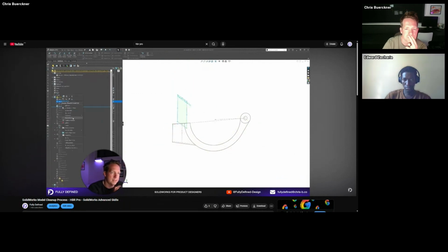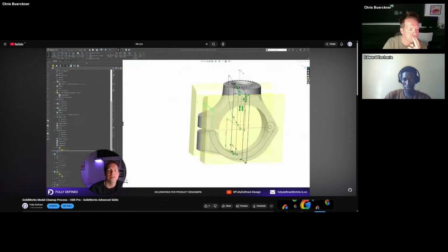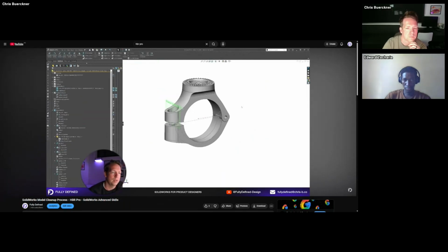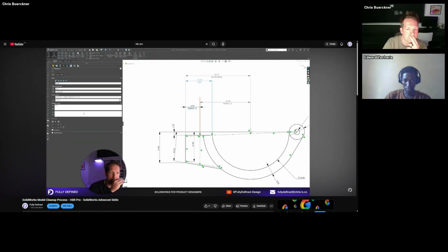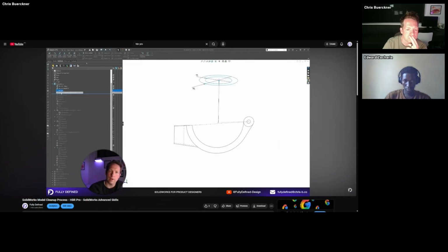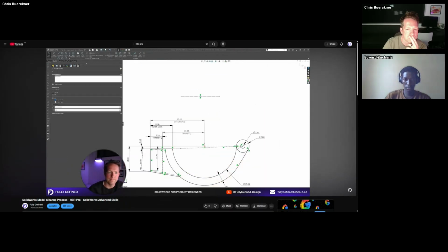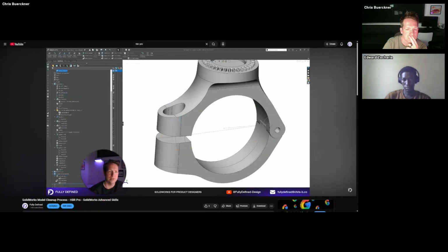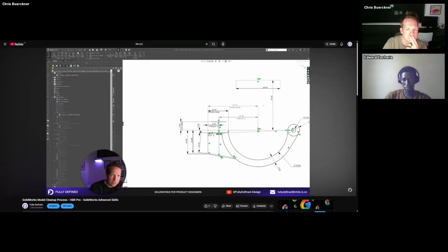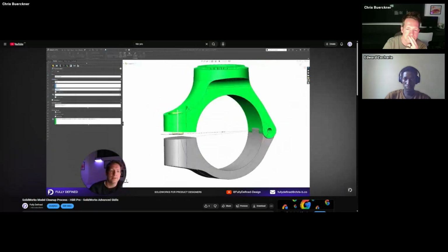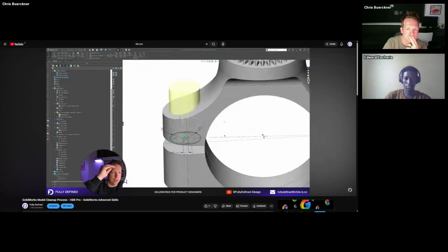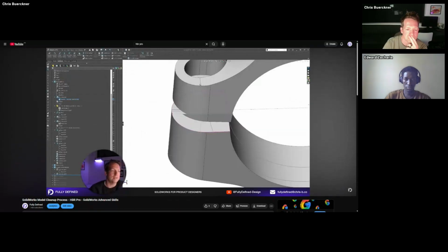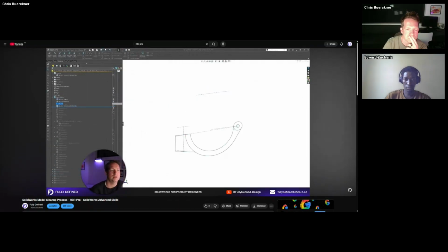First, I will identify the sketch or feature that I want referenced in the main driving sketch. Next, I will create a new sketch below that, convert the required sketch elements, so copy them, and importantly, I then delete the converted entity sketch relation. With no parent relationship associated with a new sketch, I'm able to drag it all the way to the top of the feature tree.